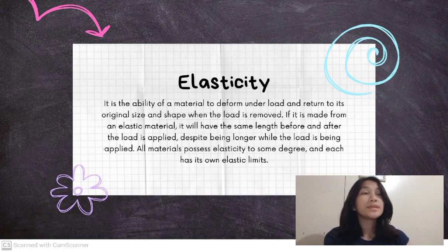Elasticity. It is the ability of a material to deform under load and return to its original size and shape when the load is removed. If it is made from an elastic material, it will return to its original size even after it has increased in size while we applied the load. All materials possess elasticity to some degree and each has its own elastic limits.